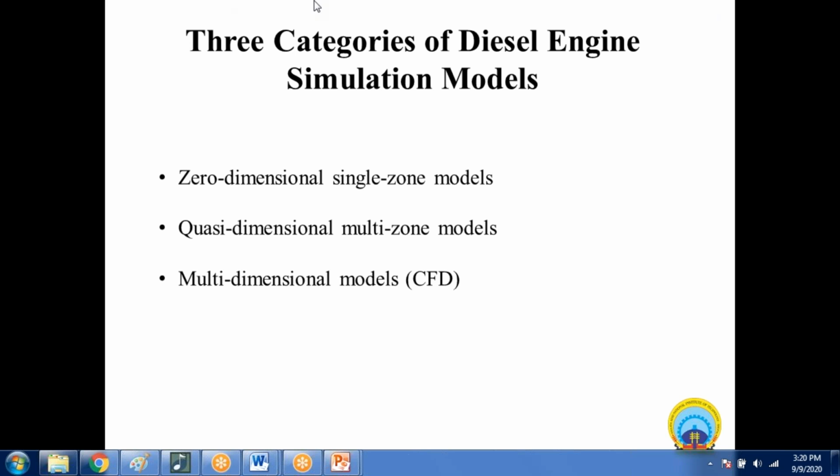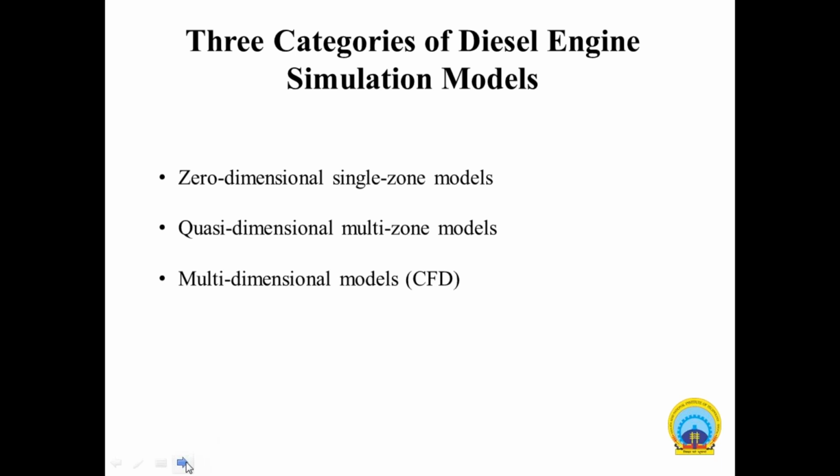So the choice of the thermodynamic engine model together with a quasi-dimensional multi-zone model of combustion, accounting for conventional and diesel combustion, is conditioned by requirements of high accuracy and high computational speed, because the number of engine simulation sessions in optimization over the whole operating range comes up to a few thousand. In earlier published papers on this multi-zone diesel spray combustion model, that is the RK model, it includes three independent emission submodels.